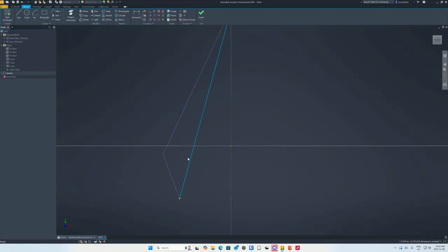And I seem to have screwed something up, so let's undo. Undo is Control Z. Undo again. Now here I can grab this point and bring it over, and I can redo. So I'm going to go back to coincidence constraint. I'm going to select that point, make sure I got it, select that point. Now I have something more resembling a four-sided object. Hit OK.